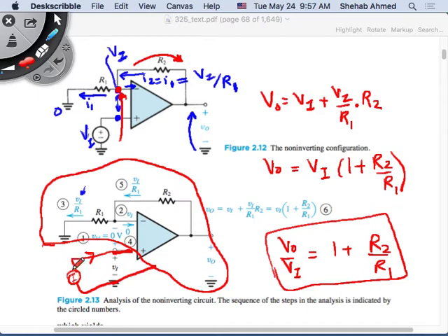So what current am I going to measure? Then our input impedance is going to be the voltage that you applied divided by the current that you measured. So what is our input impedance? Infinity, exactly, because I assume that the current flowing here is 0 for an ideal amplifier. Later we'll see that it's not, but for now it is ideally infinite. So this is a nice circuit then. I like the circuit because the input impedance is infinite. I will not load my sensor.